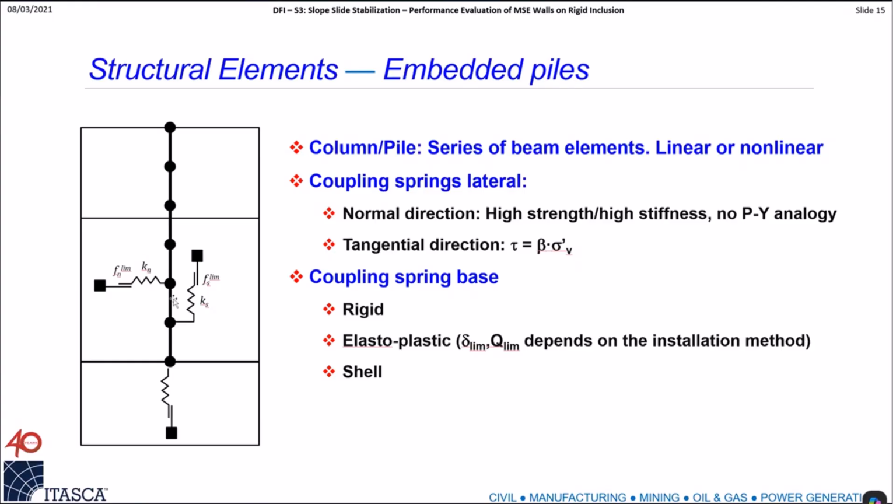In the normal direction, therefore, use a Kn which is significantly higher than the stiffness of the soil. Right now there are a bunch of FISH functions, but in the next version of FLAC3D we have implemented some utilities that read the stiffness of the soil, multiply it, and give the stiffness automatically to these links, right? And as far as the strength of the soil, you give a high value because you don't want yielding.